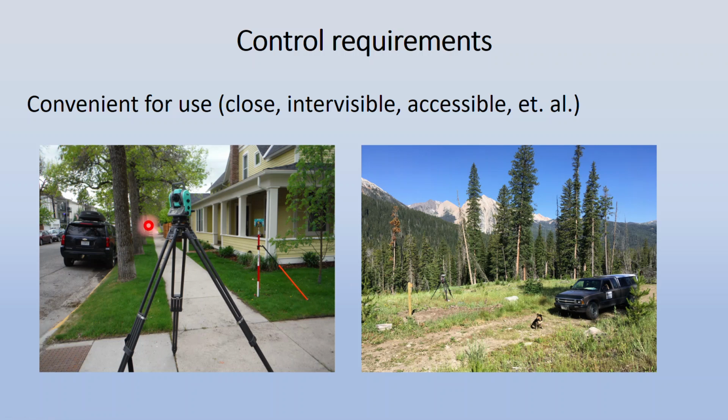So you can see the back sight is down here in the distance. I've got a traverse point just out of frame in the photograph, and I'm only shooting a foresight point about 8 feet away, 10 feet away maybe, to a property corner here. Real convenient for one person to do, real short sights which minimize any angular error that could be introduced by me or the tools in this job, and provided a really good closure on this traverse.